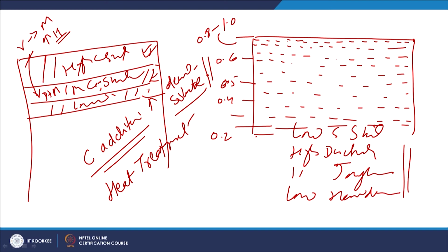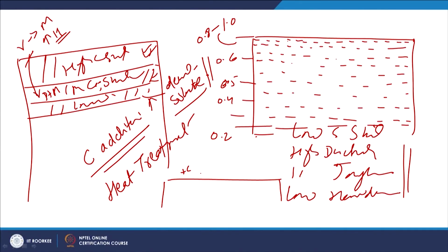In light of this, if we try to plot the variation in the hardness, residual stresses and the carbon content as a function of the increasing depth from the surface, then there will be a continuous gradient. That is one aspect. Now, how deep the carbon will be enriched during the carburizing process will be a function of the time, for how long the component is exposed in the carbon rich environment. Since the carbon rich environment is present all around the component, carbon will be getting diffused in the subsurface region.